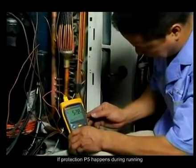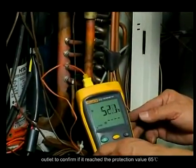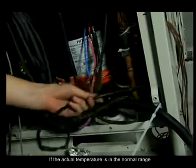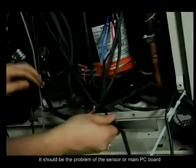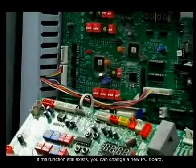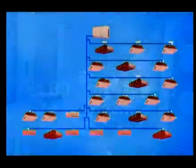If protection P5 happens during running, please use a temperature meter to check the actual temperature of the condenser outlet to confirm if it reached the protection value of 65 degrees Celsius. If the actual temperature is in the normal range, it should be a problem of the sensor or the main PC board. Please change the sensor first. If the malfunction still exists, you can change to a new PC board. If there are no above problems, please repair as follows.